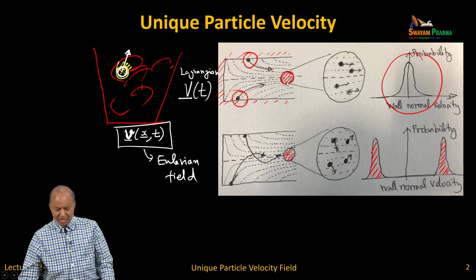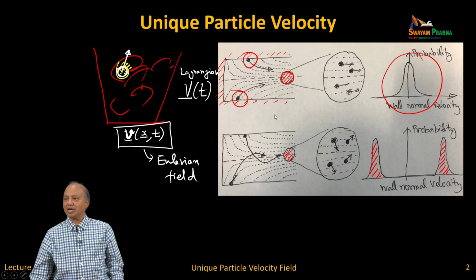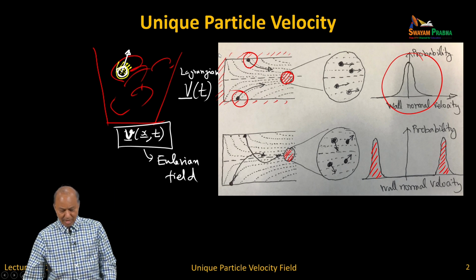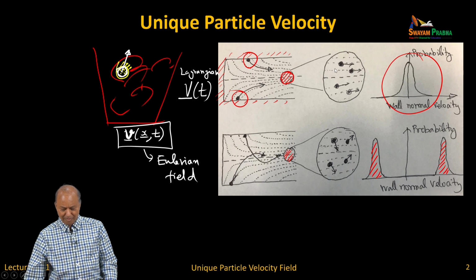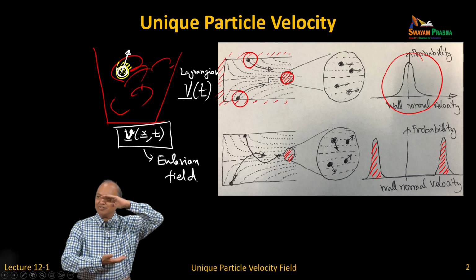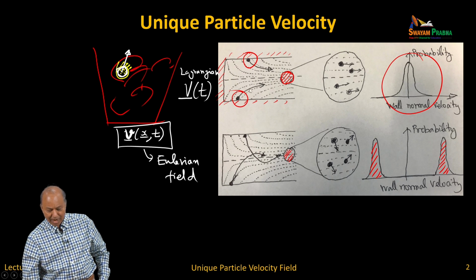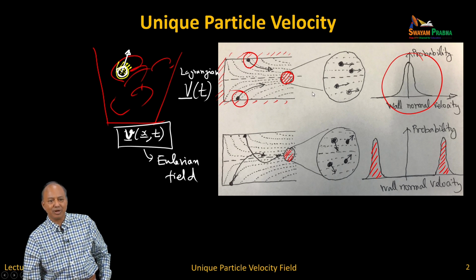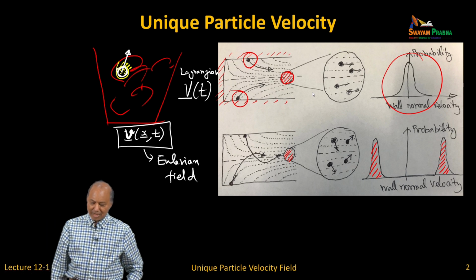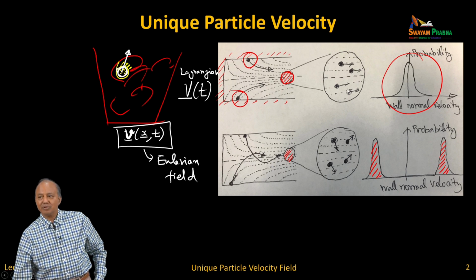So, let us take this extreme example, where this is actually a solid rocket model. Okay. So, you have a head end of a rocket and you have the body of the rocket. The nozzle is somewhere here downstream. As the surface is burned, fluid is being ejected, and let us say there are also aluminum droplets, they get ejected, they come downstream. Okay. So, there are particles, and if they are really small, they follow the fluid almost.